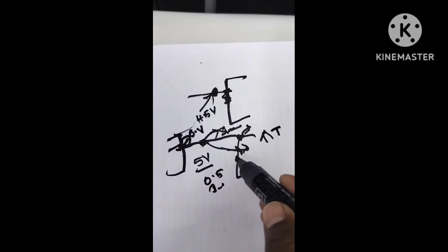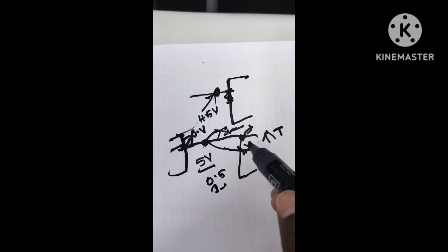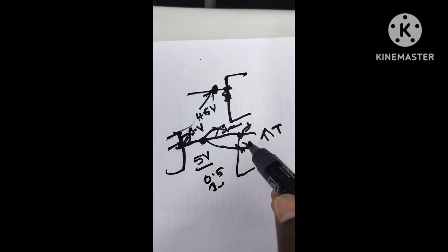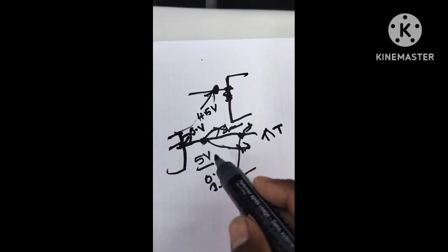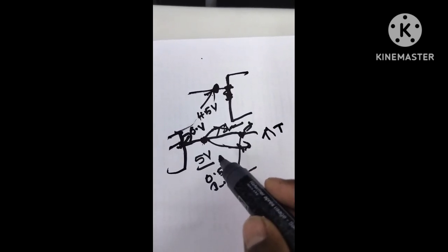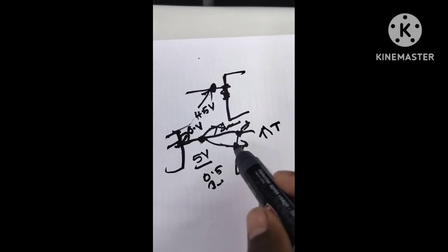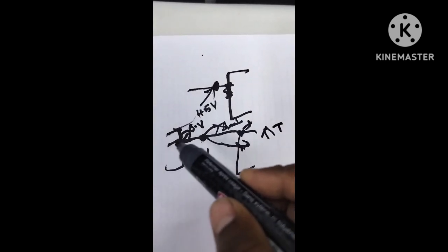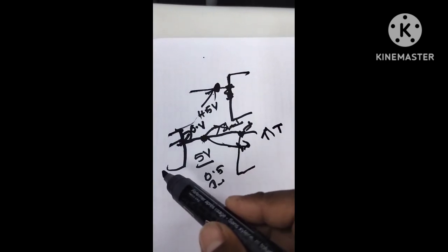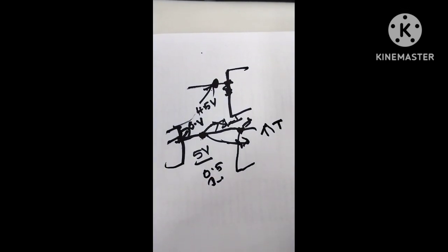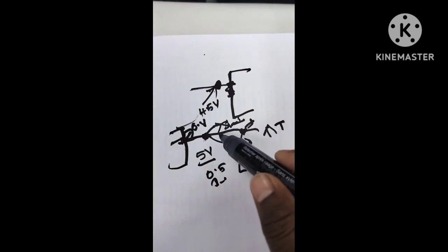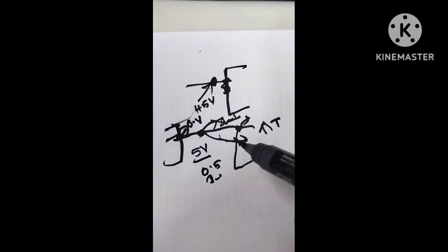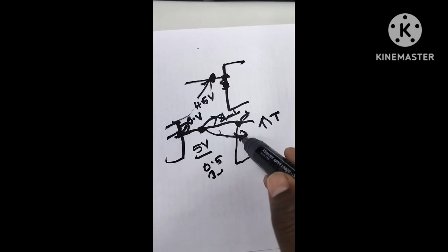As per the temperature, the resistance of the temperature sensor is not changing. So this is the information. By this way you can easily understand where you are getting the problem. Even after you short it, if the warning remains the same, you need to go for further diagnostics: check the wiring, the computer, the connectors. But for me, when I shorted this wire, the engine computer started showing temperature high, so I understood that this temperature sensor has a fault.